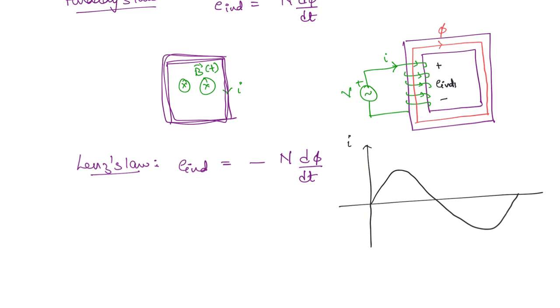Okay, so that is the induced EMF. When you give an AC, an alternating voltage, to a winding, an induced EMF is produced. Now this induced EMF will limit the amount of current that is flowing in the winding. That is one of the reasons why DC input is never given to a transformer. When you give a DC, there is no transformer action taking place because there is no time varying field, but it is dangerous to the transformer itself because in the absence of induced EMF, a large amount of current will flow, and because of which the windings will be damaged.